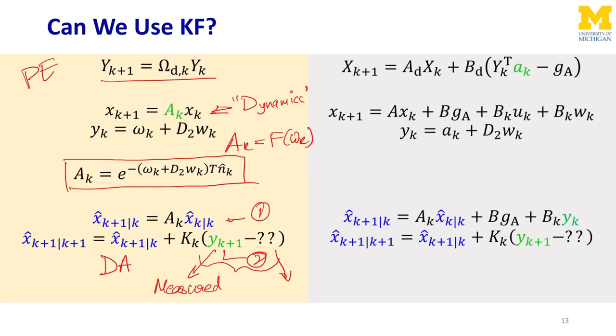It only depends on the input. So I'm going to write whatever the corresponding output of the prior state estimate equation is, which also happens to be omega_k plus the noise. So omega_k plus the noise is exactly what y_{k+1} is. And since both of these quantities are equal, this whole thing ends up going to 0.